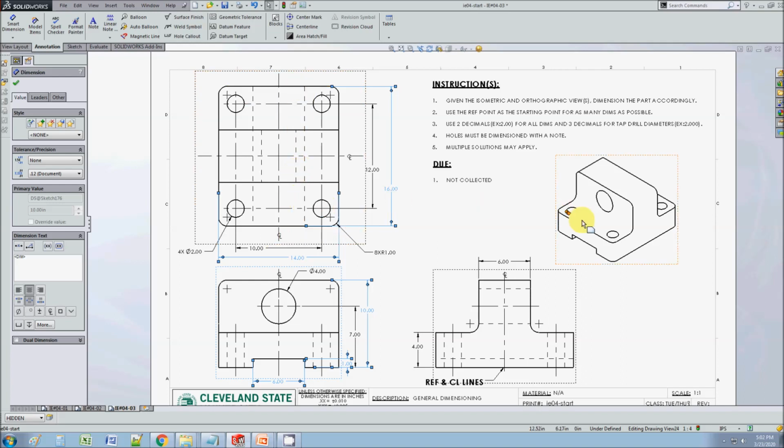Then let's see, we've got to cut these pockets out. So we're going to move our end mill up to here. Again, I'm trying to find the Cartesian coordinates of each of these points. Let's see if we can find this one. We know where this one is because we know the width of this. We know what this is, and we know it's centered, so we can do this minus that divided by 2, and we know exactly where this point is. So we know where that is, we know how wide this is, and then we are good to go on this shape. We also know what the fillet is based on that.